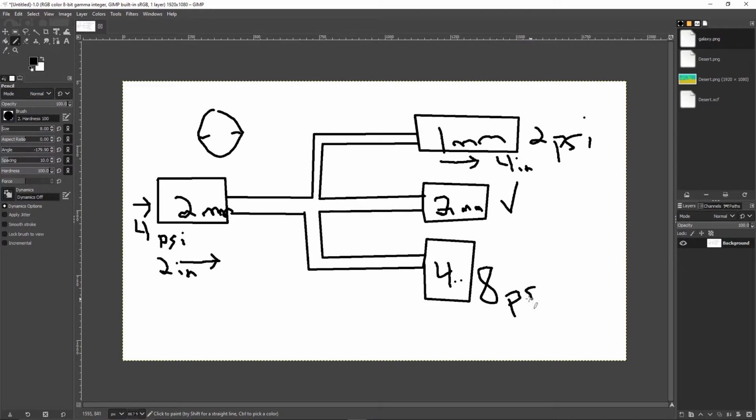You've got a really heavy pressure plate and you're trying to move it, and the springs are just really stiff. Well, the clutch pedal is going to move a lot, but in reality, this pressure plate doesn't need to move very much. So this is a great example of how we're going to use hydraulic fluid to create mechanical advantage.